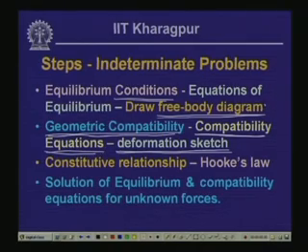Now, once we write down the equations of equilibrium and the equations of compatibility, with the help of the constitutive relationship, which gives us the relation between the strain and the stress, we can write the stress in terms of the forces. So, we have equations of equilibrium written in terms of the forces, and we have the equations of compatibility written in terms of forces through Hooke's law, the constitutive relationship.